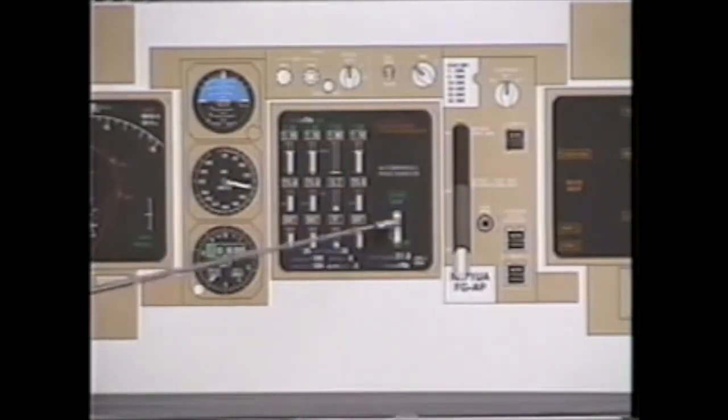The landing gear indication, in this particular case, is a single indication because all 5 nose, body, and wing gear are down and locked. If a landing gear was to encounter a problem, this would automatically expand into the expanded display, showing each specific gear. Flap indication, we're in the primary drive, everything is working fine, so as a result we have this single vertical tape indication on the flaps.